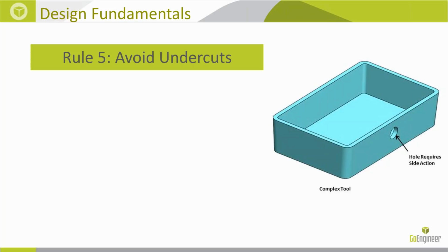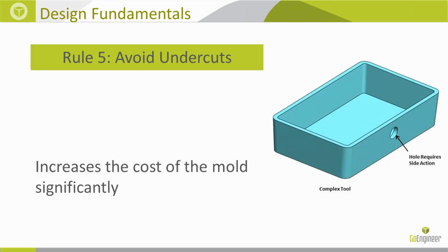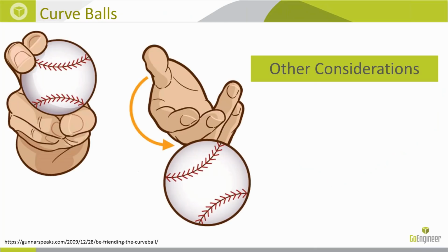Basically, like in this case, it would be like a cylindrical boss, that sits there while the material's flowing around it. And so you now have like a whole other section of your tool, and then you have to remove that section and then separate the cavity to release the part. So not only is it more tooling, but it's a secondary step in order to release the part. So you're increasing the cycle time, increasing the cost of your mold. So if you can implement some creative ways to get around that, you can keep the cost of the mold and the tool relatively low. So it's important to avoid that.